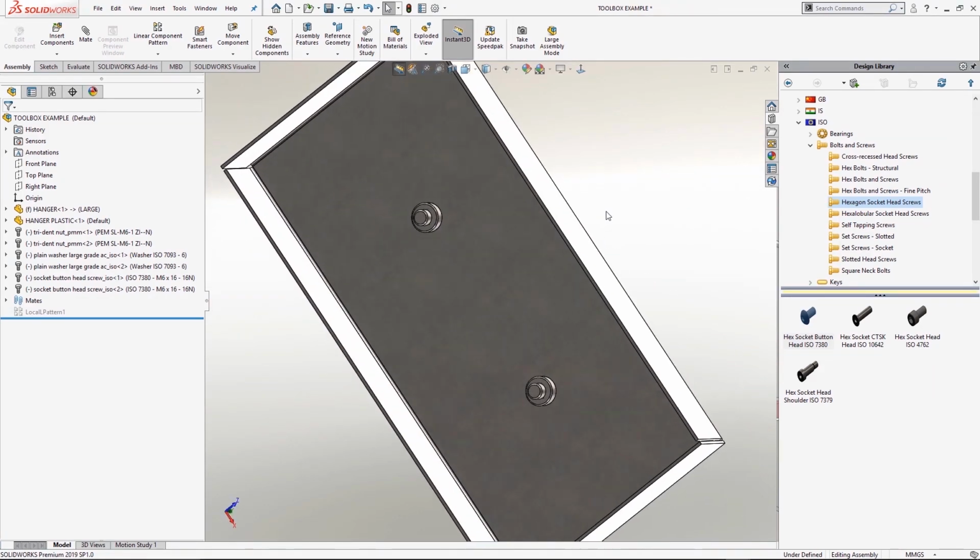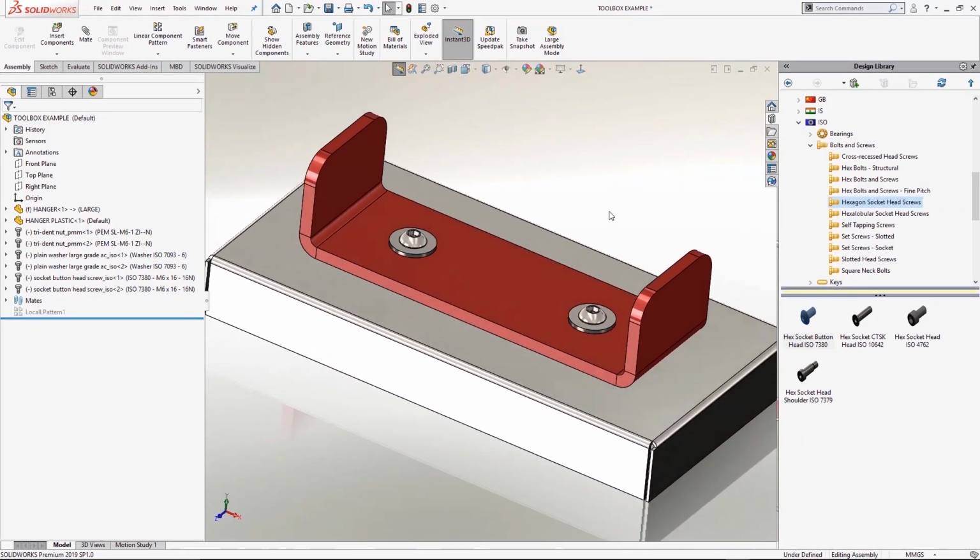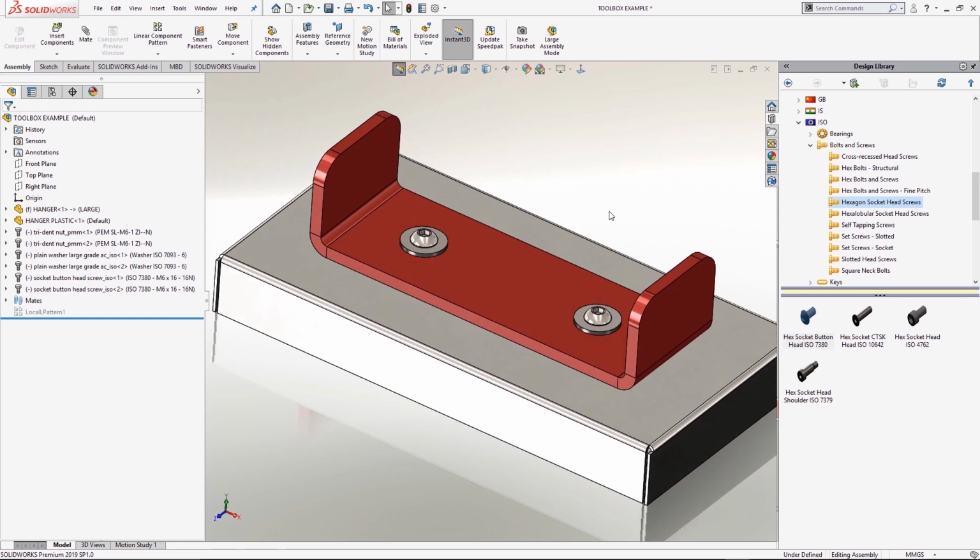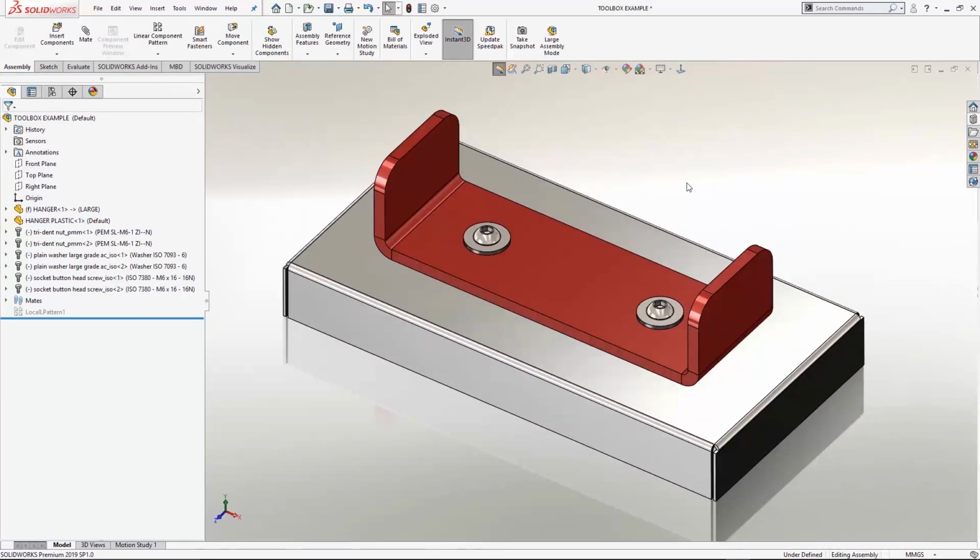But as you can see, really quick and simple to add all of our nuts and bolts that we might need to the design, and also that's including the bill of materials, the specification as well. Now we can customize that toolbox, so these things have got costs associated, or maybe it's a part number that's specific to ourselves. So a really nice way of being able to use our SolidWorks toolbox.